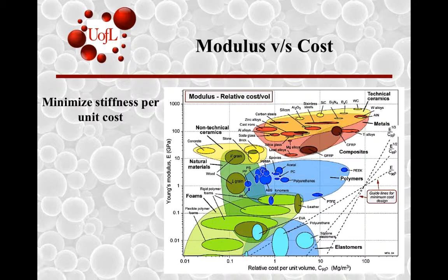Since in a lot of designs, mild steel is often the starting point for consideration, and because of its cost attributes, doing a ratio between the cost per kg times the density of the material and cost per kg times the density of mild steel will allow to get this type of a relative cost estimate, and that's the basis of the x-axis.